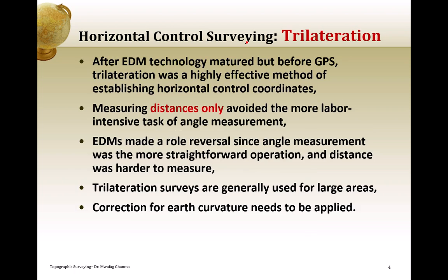A requirement is that we have to come up with initial values of the easting and northing of the unknown stations. In the old days, there were distance measurements and angle measurements. The angle measurements were much easier because measuring distances would be over long areas and all over the place, like mountains and depressions, whatever. So it was very difficult to measure distances. So we used to prefer the triangulation over the trilateration. In the triangulation, we'd measure one baseline accurately, and that was enough effort to be measuring distances.